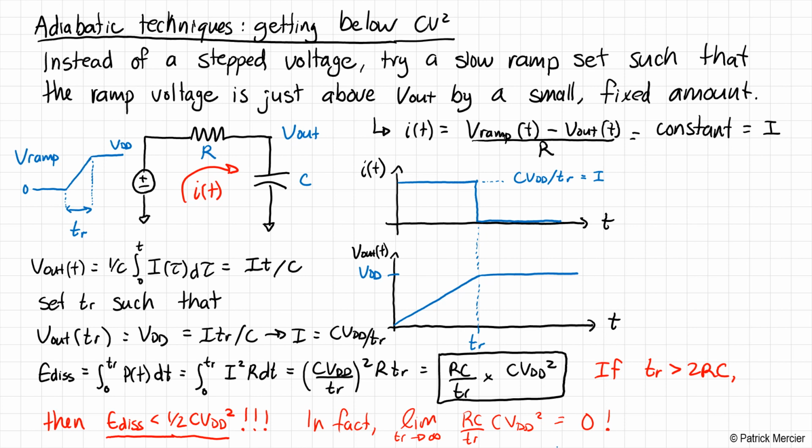Now, with that said, there are some interesting applications where this is possible to do, and we can indeed get significant energy savings. This is particularly true, for example, for clock driver networks, which don't have logic associated with them. They just generate square waves to clock flip-flops and so on. In fact, my own research group has published work in this area that has shown that we can indeed save significant clock power through some adiabatic approaches. So as I mentioned, adiabatic techniques are really interesting, but unfortunately, this is exceedingly difficult to implement in practice.